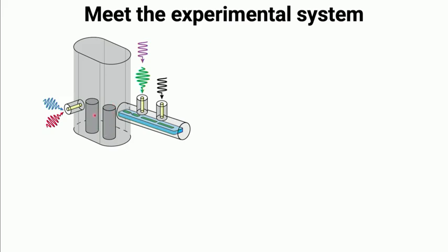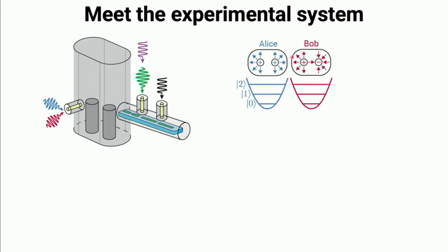Each of those posts hosts a quarter wave electromagnetic mode, and because there are two of them, you have two eigenmodes in the system. And here I'm just sketching the electromagnetic field distribution of those two modes. And these two modes are going to be my harmonic oscillators, which I'll use to encode the dual rail qubit.